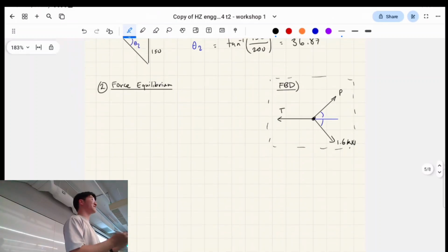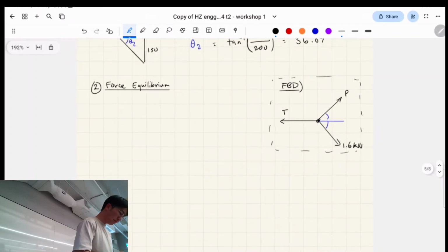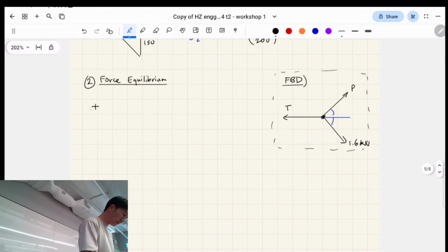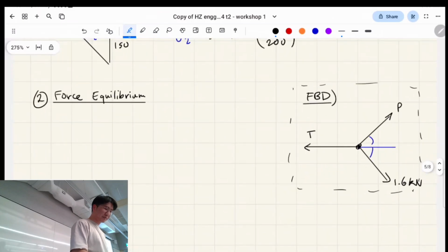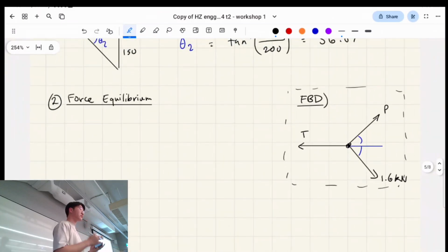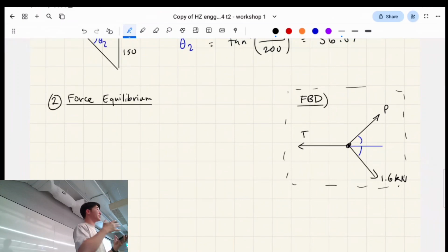So now we're going to solve for these arrows because they're in an equilibrium, they're not moving, right? Okay, actually, I've kind of given the answer away. Basically, if we look at our free body diagram closely, the two static equilibrium laws that we've learned so far are the sum of the forces in the y direction and the sum of the forces in the x direction, right?